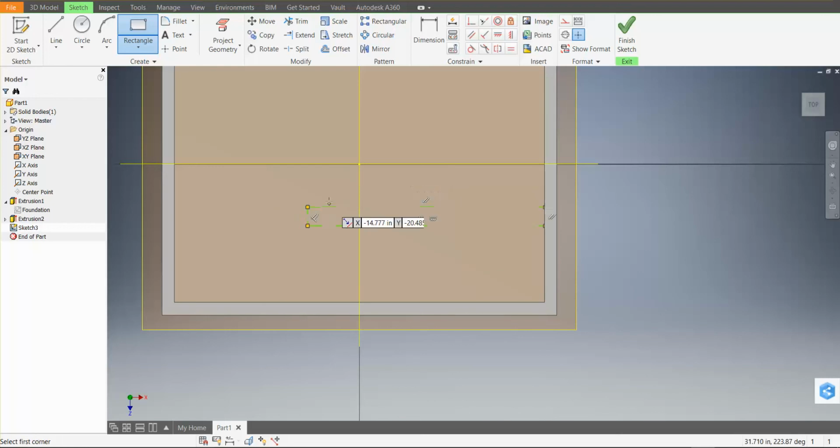And here's our inner wall. We'll dimension this to be 6 feet. Oops. And notice how it moved there. Okay, so if we dimension that to be, like I did, 6 times 12, there's no constraint there. There's nothing that is saying that those are constrained to each other.